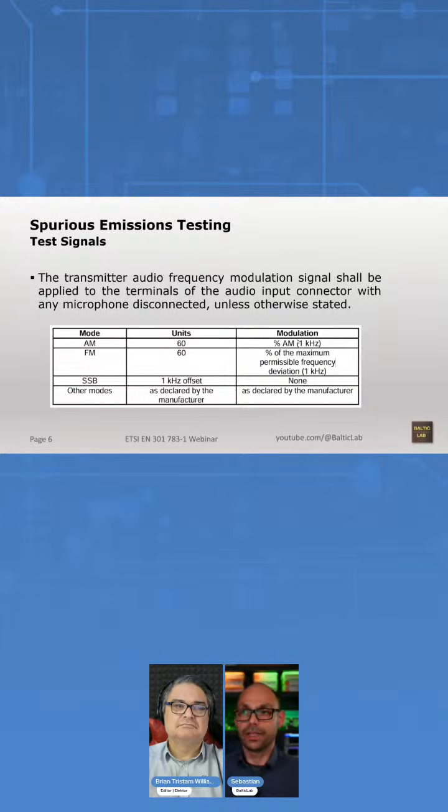The next thing I've never seen, and this is really different from the United States. In the United States, the rules that the ARRL uses in the lab is to use unmodulated signals. In Europe, you should use modulation that simulates voice and the entire spectrum that you would usually carry, but only if it's a non-constant envelope modulation. So AM, for instance, or SSB, the envelope of the signal changes by the modulation, and the exact characteristics of these modulation signals is shown here.